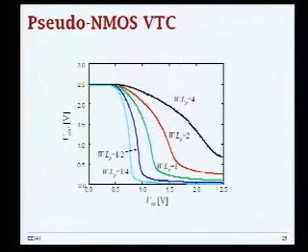Here's the result. If you plot your VTC characteristic and start with a very strong PMOS, your VTC is not going to look good, because your NMOS is not going to be able to pull down enough. You spend most of the time at VOH, or close to VOH. You're not going to be able to fight that PMOS and pull it down.